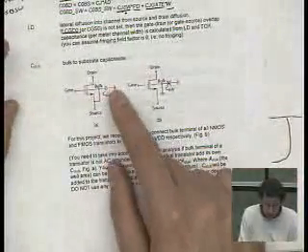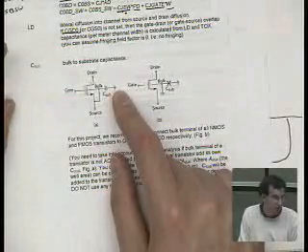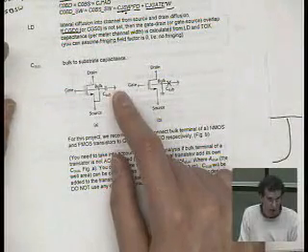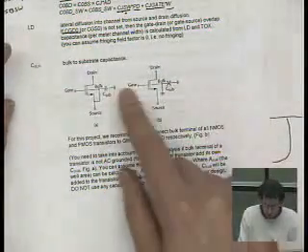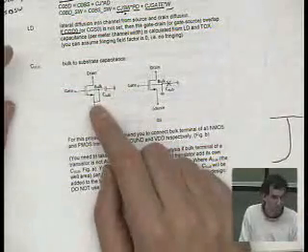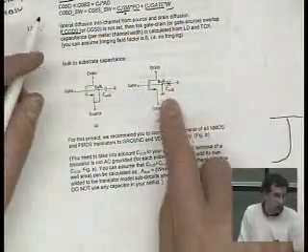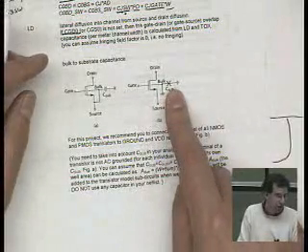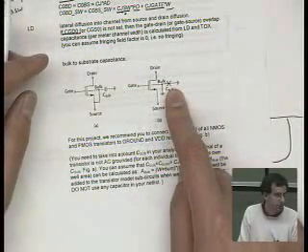There's always a bulk to ground capacitance, to the universal ground. And if you connect the source to bulk, you're effectively connecting that substrate capacitance to your source node. Whereas if the bulk is connected to a small signal ground, this substrate capacitance doesn't manifest itself.